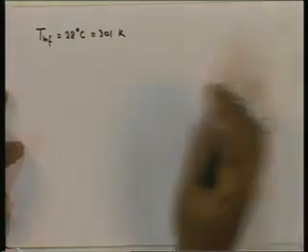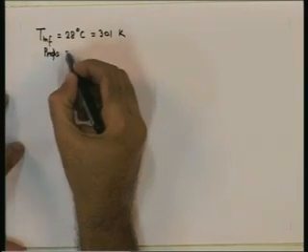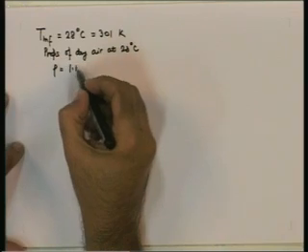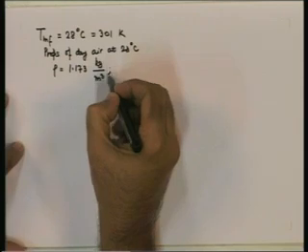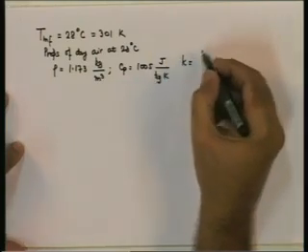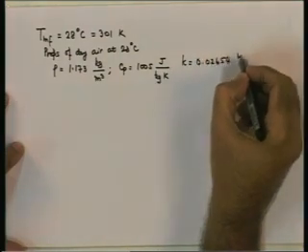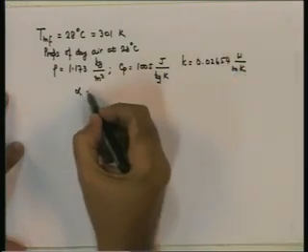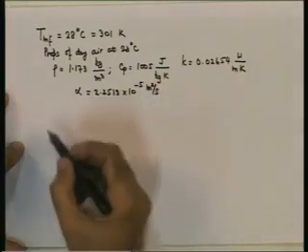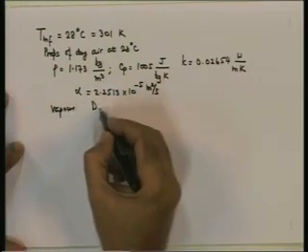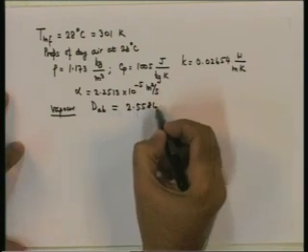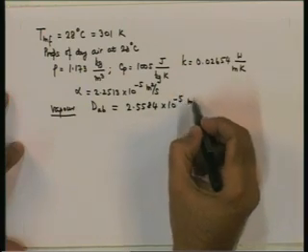The air is moist, but the moisture content is small, so we will use properties of dry air at 28 degrees C. These are rho, Cp, K, alpha, and for vapor we obtain DAB at 301 K to be 2.5584 into 10 raised to minus 5 meters square per second.